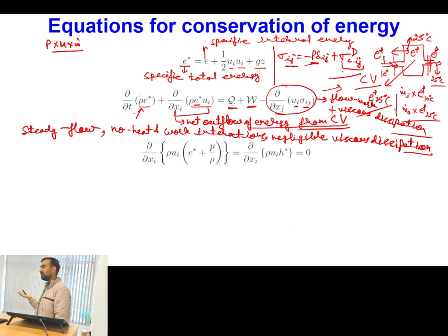Is this point clear? Because this is the viscous stress tensor, and whenever it is multiplied with velocity, it represents the dissipated energy content. So once I write negligible viscous dissipation, this sigma C content will be 0. But which term will be left? Minus of del by del x into P. All are clear with this idea?